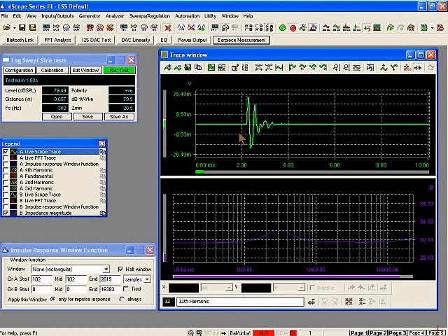If we use a broadband stimulus like a noise signal, a speech file, a multitone, or this log chirp that I'm using at the moment, we can derive an impulse response without actually having to play an impulse through the system. So this gives us much greater energy in the test stimulus and much more resilience to background noise.